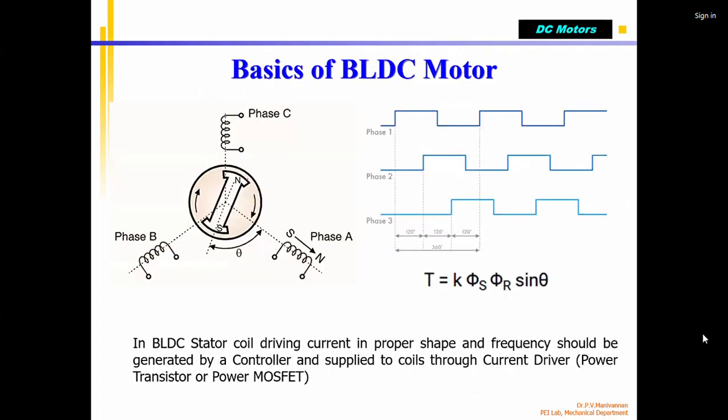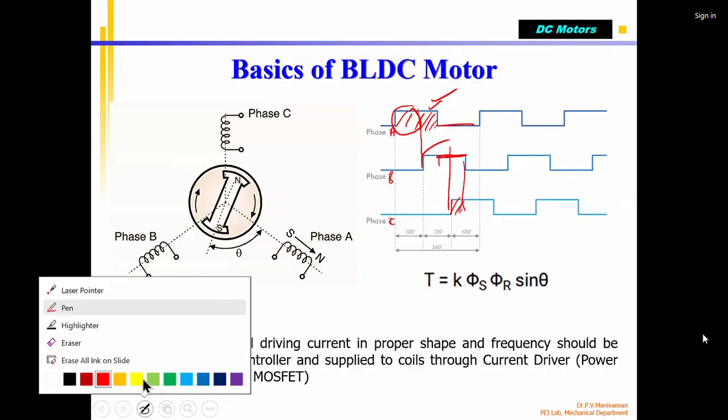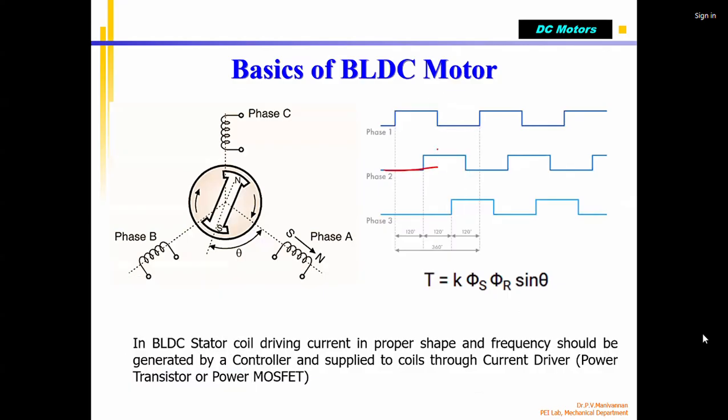Okay. I already told you that 3 coils are energized one after another with a particular signal. See, this is on, correct? Up to this period, only coil A is on, and the remaining 2 coils are off, correct? Then this also turns on, the second coil starts. After this time, the first coil, A coil, we can call it A or B or phase 1, the voltage becomes 0, but the B coil still has power. After some time, the C coil kicks in. Right? You can see that this is called overlapped. Correct? It is not one after another. The simplest thing will be like this.